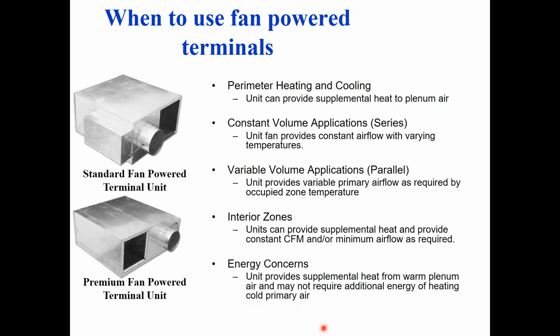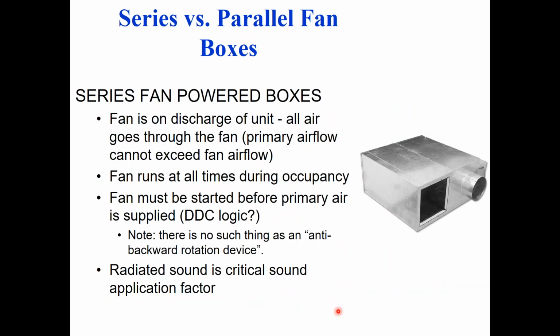So if you can get the quote-unquote free plenum air as your first stage of heat, and you can at least be net neutral on the fan energy, then these guys can be more energy saving than a single duct box with reheat. Let's look at these guys here. Oops. So here's a series box.